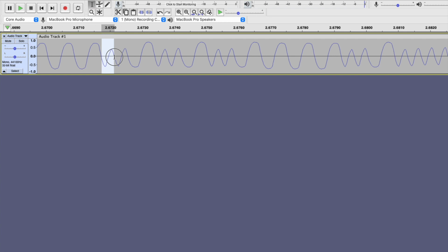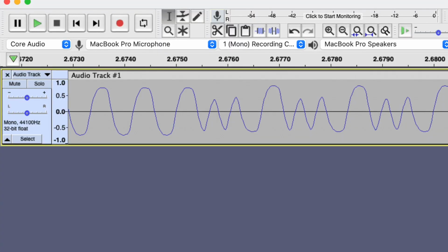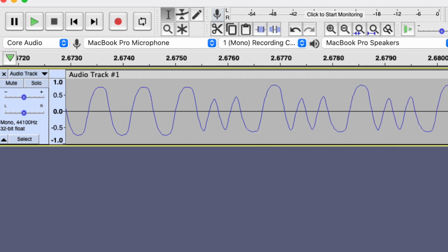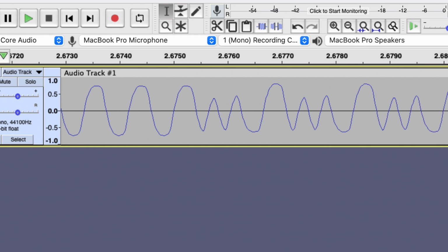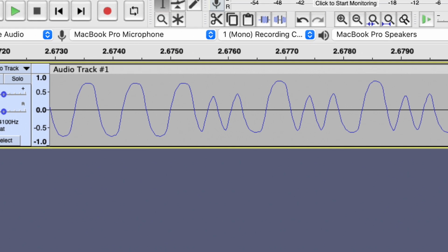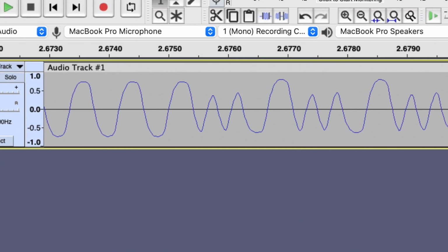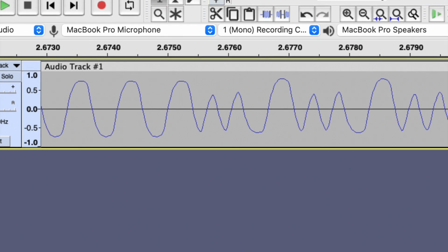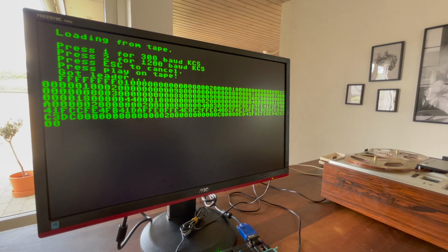To speed things up even further, you can skip the second 2400 Hz pulse, making the data a bit more uneven by making ones take up half as much tape as zeros. If 50% of the bits are ones, this will increase the speed and capacity by 25%. Another way would be to use only the half waves, changing the frequency at every zero crossing instead of just once per wave. For the 6502, this is certainly possible to keep up with by simply changing the active CA1 edge while receiving the data. A third way would be Lancaster's suggestion of simply doubling the audio frequency.